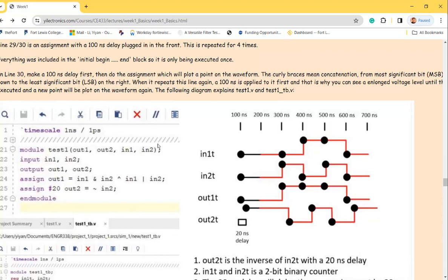So is the 20 nanoseconds within that 100 nanosecond block, or is it added on? It's within. It's on the same line. It's within the same 100 nanosecond time block, because that's the time period of your output signal changes, right? If that changes, it's going to change the signal being injected into the chip. So whatever the chip is doing inside doesn't affect the outside force, right?